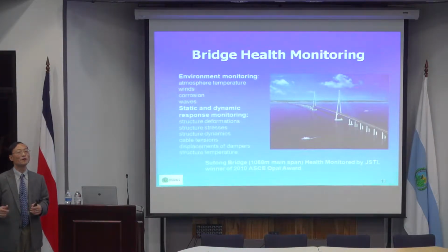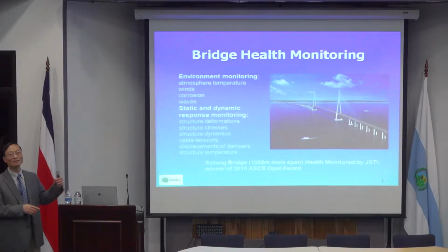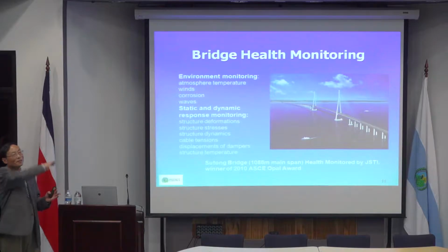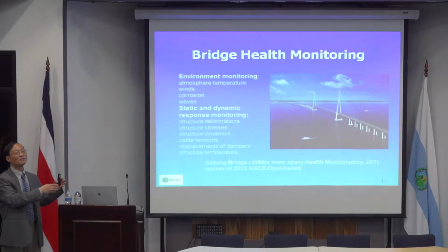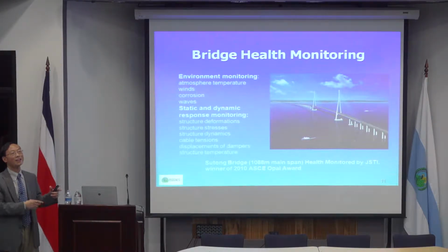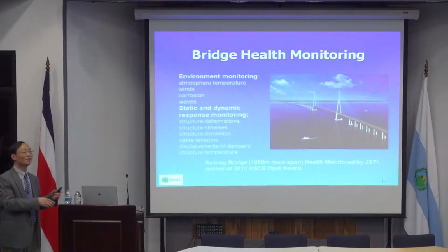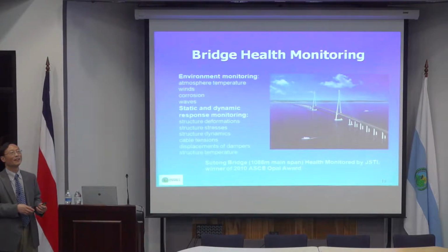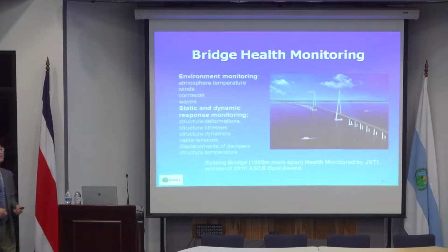Once you've done that, the live load distribution factor for individual girders will become individualized. Once individualized, it's not just an envelope, so that will give you a much more accurate prediction of how much live load will be acting on that particular element. And that typically will reduce your stress significantly, approaching the reality of the stress.